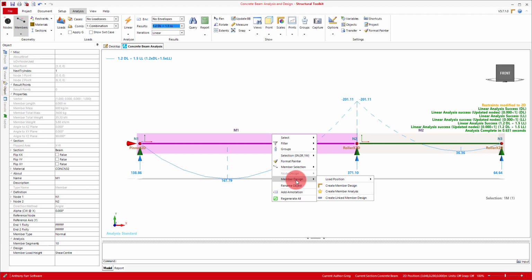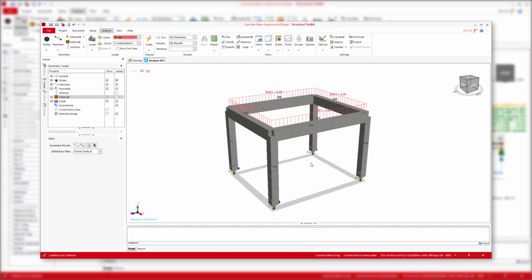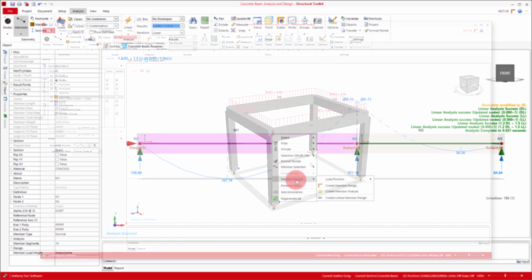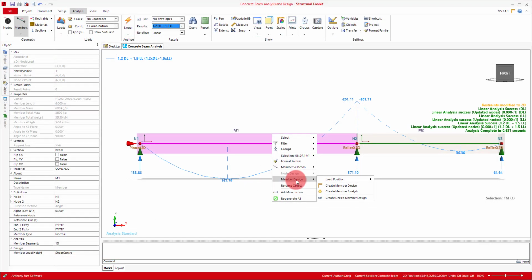You can also convert individual load cases to a design only, but not to any analysis. Now, when we say a valid beam model, for concrete in general terms we mean a 2D spanning beam from support to support. You won't be able to convert a 3D model of any kind. So in our case, we just have our single load combination on, and with our beam already analysed, these options appear.